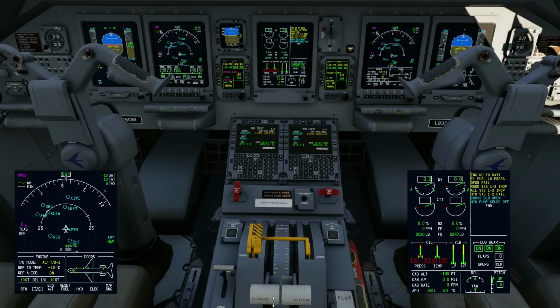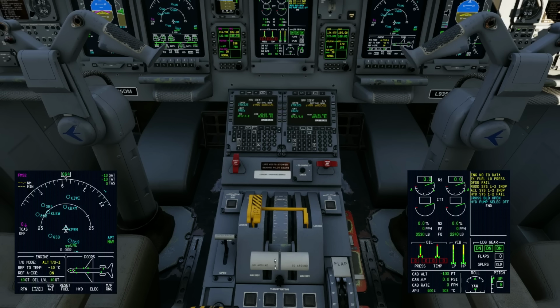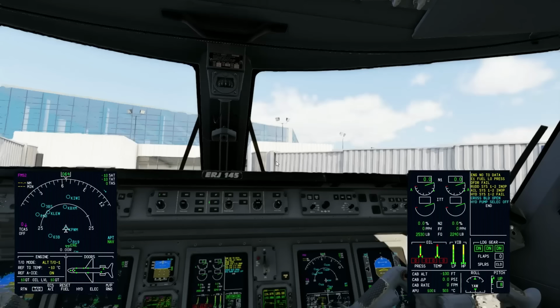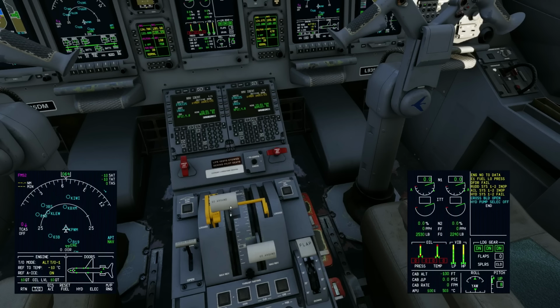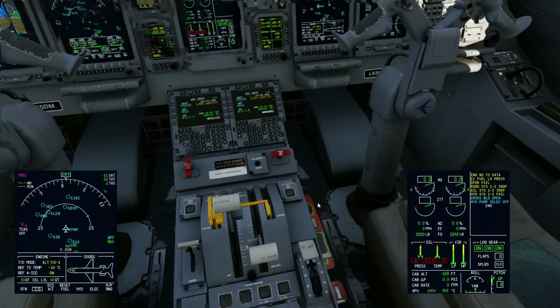The gotcha is that the thrust levers need to be in idle before you can start or stop the engine. This is a safety feature because you can imagine, right, if you're flying around with your thrust lever up, you do not want any possibility that you can turn up and accidentally or maliciously try to turn this off. If you select stop with the thrust lever not in idle, nothing's going to happen. Engine's going to keep running all day.